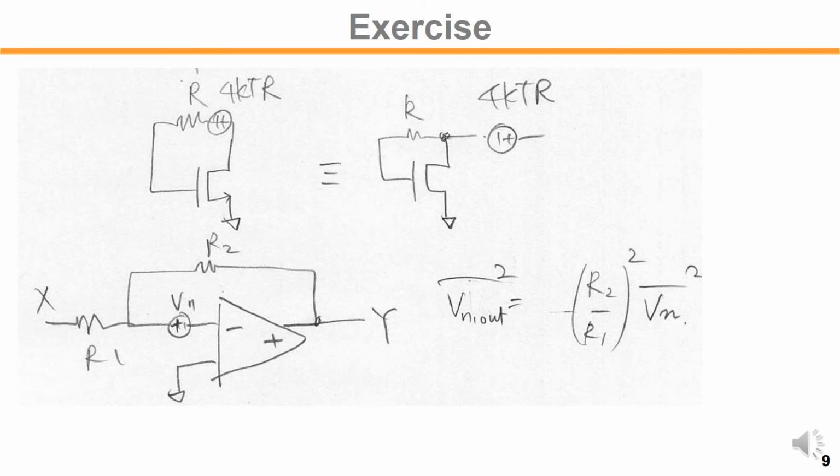These are some of the exercises that we may think of. For example, the diode connected load. We have, let's say, resistor feedback like this. We have the resistor noise 4kTR, right? The mean square noise voltage Vn squared would be like this. Since this is inside the feedback, the drain and gate are connected through the R, so the noise can be just taken out of the loop like this.